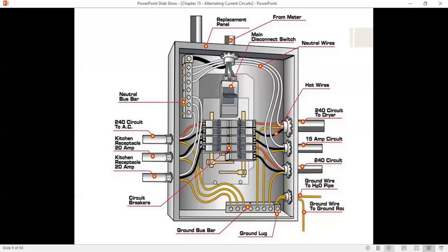That's the reason why we alternate red, black: if we're going to use both circuit breakers, if we're going to use the whole 240 volts, then we need both hots next to one another, thus the need to alternate.